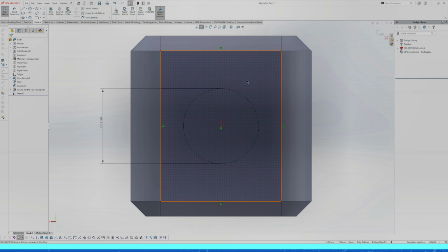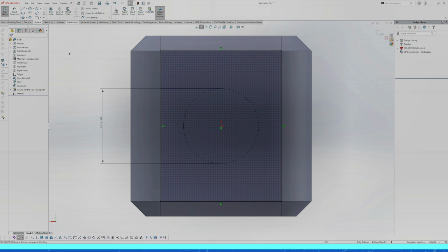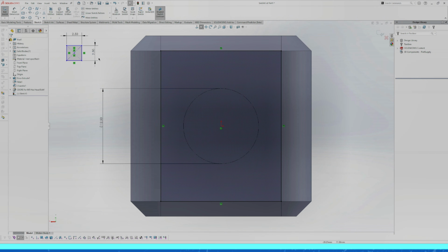All right. So now I just need to make the squares. It's a little bit of a process, but I do have the height and the width of the squares, so they are 2.5 millimeter squares. That is good to know. So I'm actually going to go out here and make the square. And now you'll notice that we made the square, we've given it dimensions, but it's still blue. That's because it's undefined. It's in nowhere space. And I want it to be defined such that it's on the tangential line of the top of the circle.